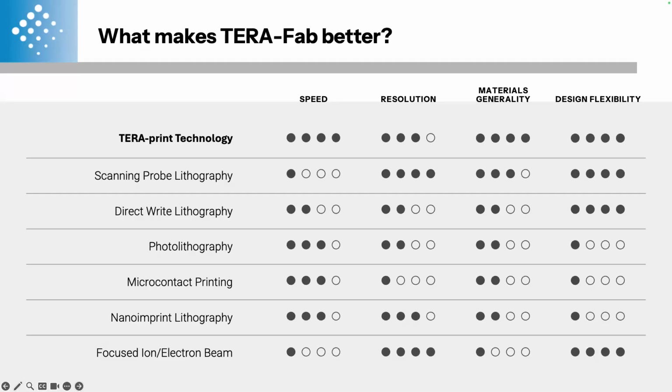We also have high uniformity because BPL delivers light directly through tip surface contact in the near field. The pens automatically compensate for local substrate height variation, providing more uniform feature quality than conventional projection-based tools.